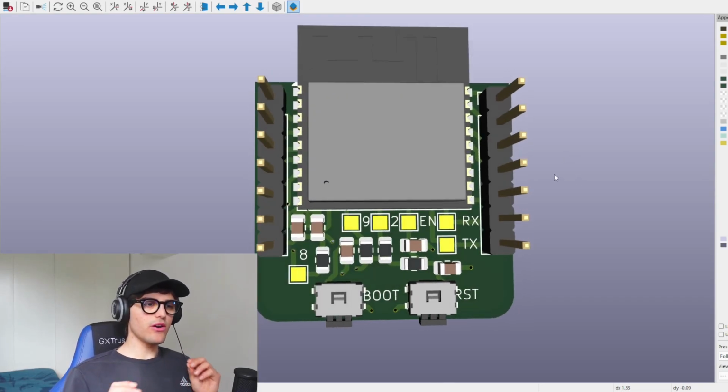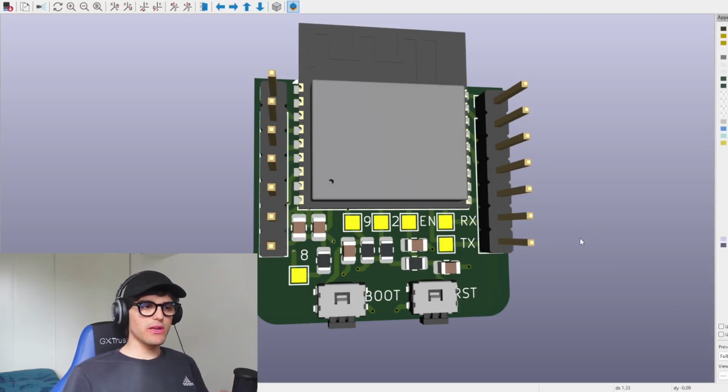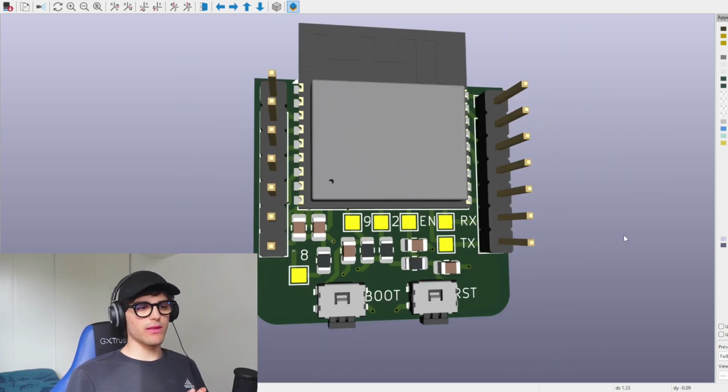As you can see, there are a lot of components missing that are usually on the dev kits that you have seen before. This is because I didn't want to use this board to prototype any of the project, but rather to see if this board and these circuits will work on this PCB right here. For example, in the final PCB for the Enki hardware project, I wanted to use the RX and TX with the boot button to upload my firmware into the module. With this board right here, I should be able to do the same and see if it works. As you can see, I also added these two test points for the two signal paths.